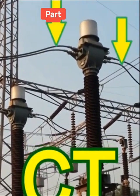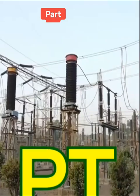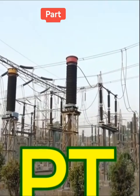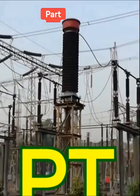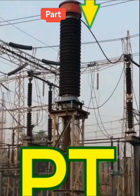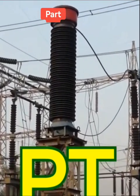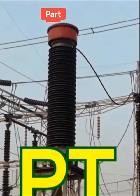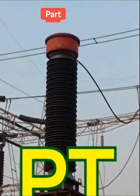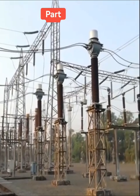But now your VT does not have that, right? Your VT only has one connection point, which is that one. So this is how you identify between the two. And VTs are always connected in parallel, and CTs in series.